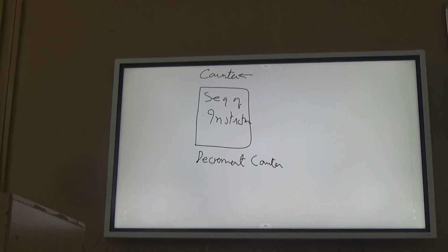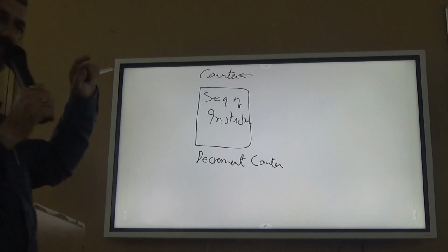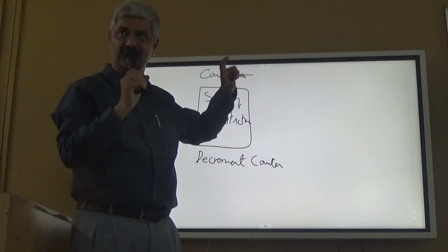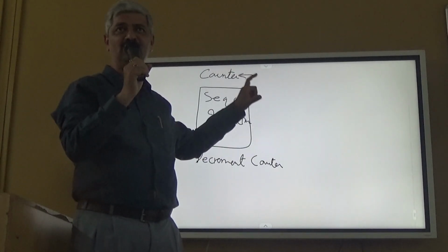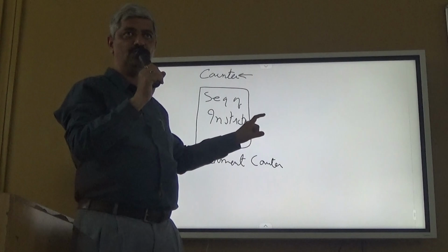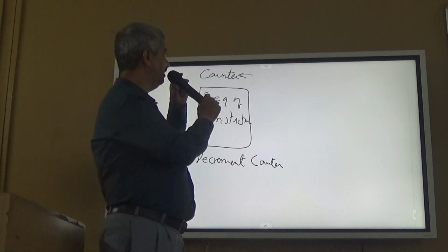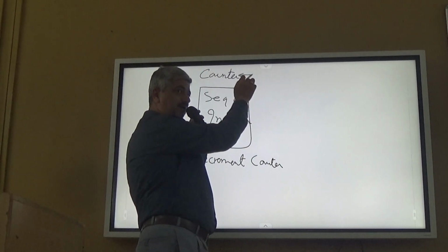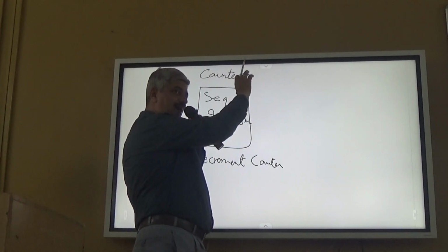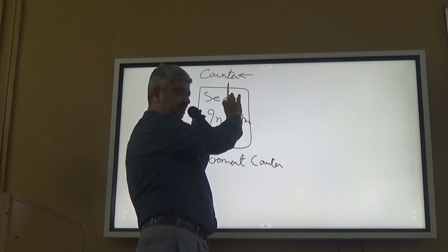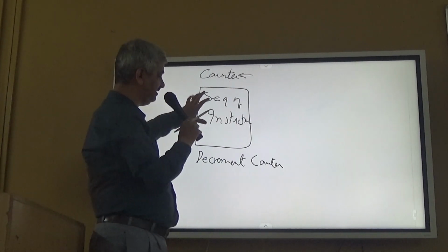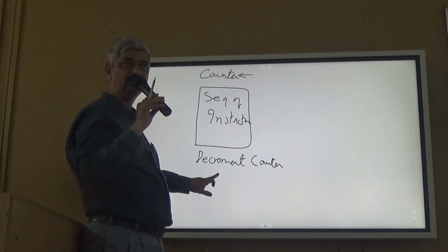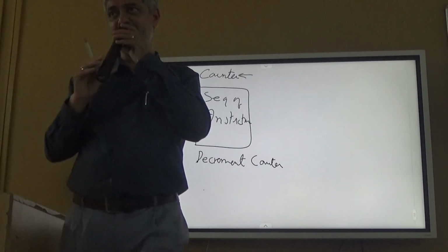I want the microprocessor to execute a group of instructions a repeated number of times. I can repeat it as I want, but that would be a non-smart way. So I will initialize some counter by the value for which I want this to repeat. Once it is done, I will decrement the counter, and then what will I do?